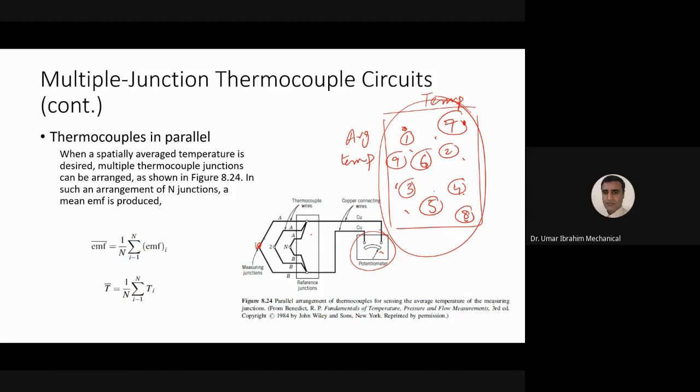उसके बाद जो है we studied how to use thermocouple. We discussed reference junction, that we can have the reference junction at some known temperature or at some fixed temperature, or we can use another temperature measurement device to measure the temperature of a reference junction. Uske baad we discussed how can we convert the voltage output of a thermocouple into to find the unknown temperature.